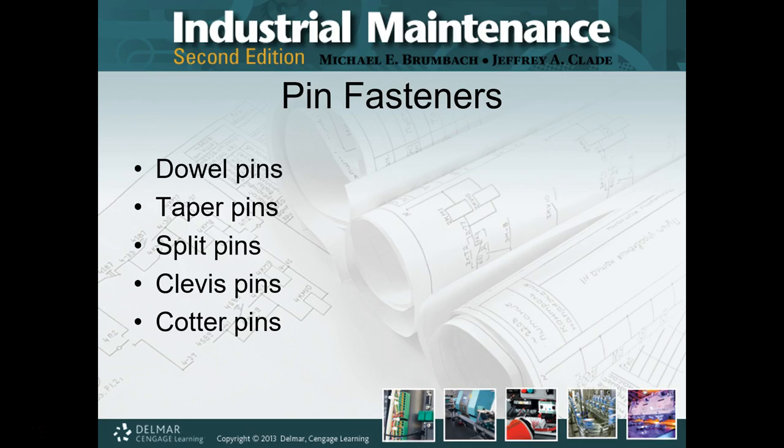Work with me. The two long legs will slip through the hole, and then you splay the ends out on the other side. If you put a cotter pin through a round stock, you tend to take the ends and roll them around the round stock, which keeps them out of the way, and you know the pin's not going to fall out. If it's a flat surface, you try and keep the pins as flat as you possibly can.